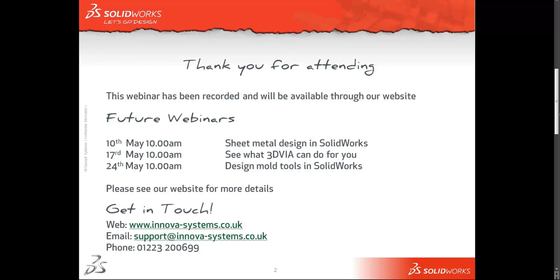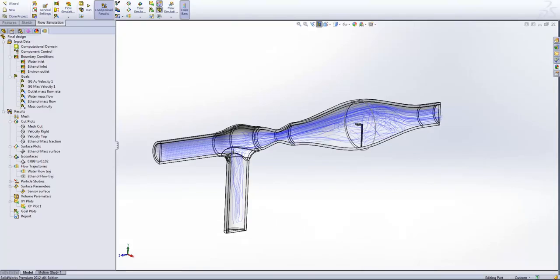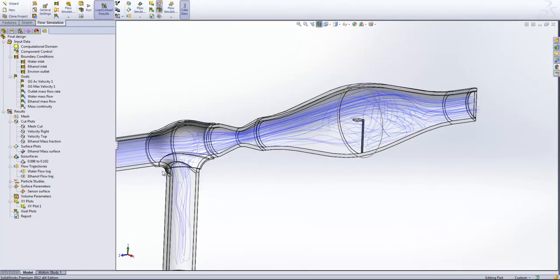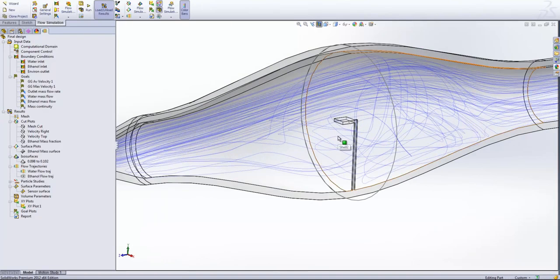Can I analyse the stress due to the flow? I'm going to assume that you mean, can we analyse the stresses as a result of the forces resulting from our flow studies? So, for example, if we switch back to our study here, we've got flow impinging on the front of this sensor, which would be pushing against it. We've got a force generated in the streamwise direction. So we would be getting stresses in the stalk that is holding the sensor up, for example. The answer is yes.